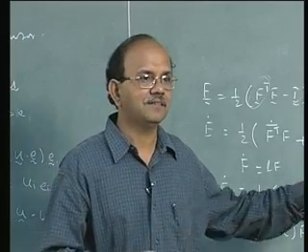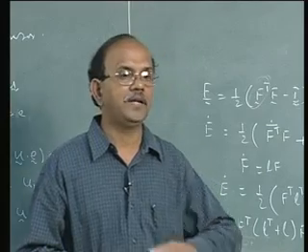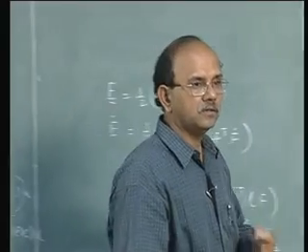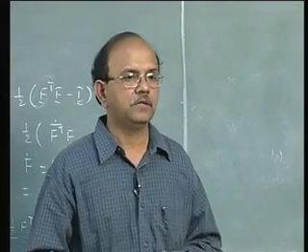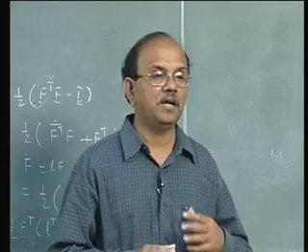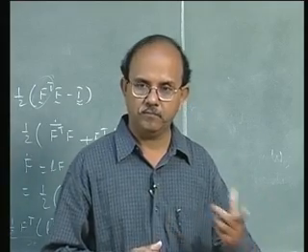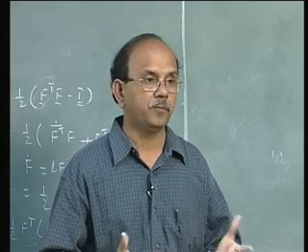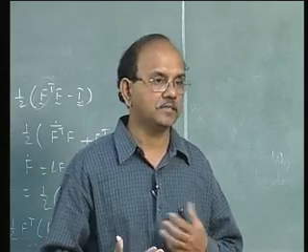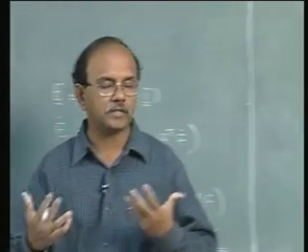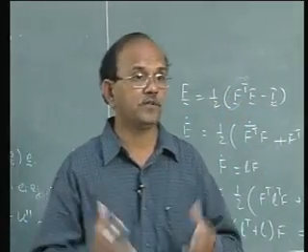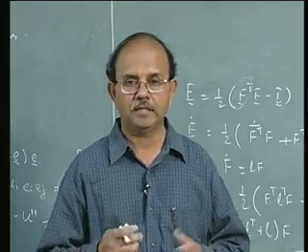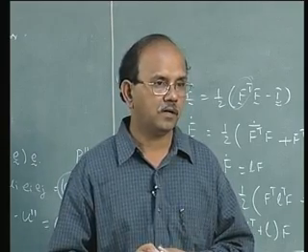Is it that this L had been additively decomposed in a very nice fashion like that, and is it that we have in D a quantity which represents purely stretching, and do we have that quantity W to represent only the rotation? That's a very important thing to understand. Do these two types of splitting of the deformations lead to the same result? So let's see that. Let us see what is the relationship between R dot and W.